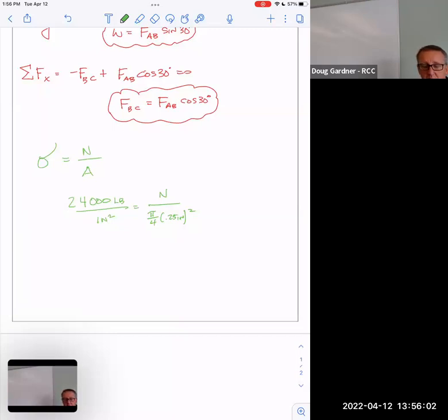That normal force would be the force on BC, correct? That's exactly right. So what I called N here is actually the same as BC. In a sense, my labeling system wasn't all that great. Maybe if I had started with this green one, then instead of calling that force BC, I might have just stuck N in there, so to speak. But the point is, this is going to allow me to solve this. And so if I solve that, I get that N there is 1178.